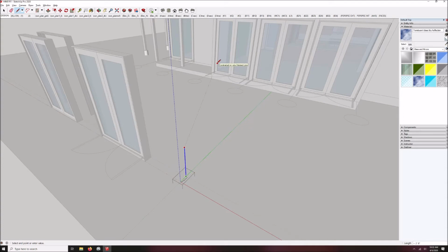and I'm going to type in 7 foot 11.5 inches and enter. Now I'm going to go in the red direction, 5 foot 11 inches, and again in the vertical direction using my arrow down to the ground surface where we started. Okay, that's my path.